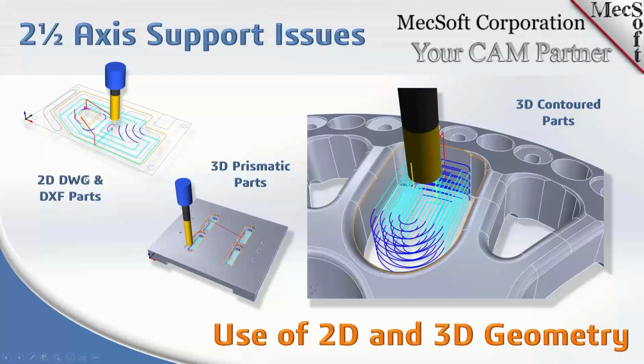If you have a 2D drawing, such as a DXF file or something you've drawn inside of Rhino or inside of VisualCAD, you can machine that in 2.5-axis and control your cut depths and everything manually using the dialogues. You can also machine prismatic parts. Prismatic meaning basic parts that have vertical side walls, no contoured areas, basic two-dimensional parts. As you see here on this particular image, we've got some slots and pockets and whatnot.